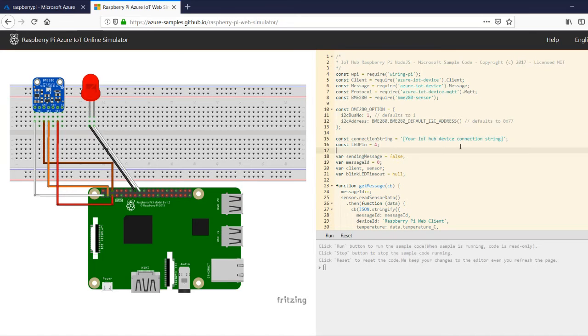Now just to give you a brief overview, this little box here is a Raspberry Pi. Like I was saying, it has 4 USB ports, 2 here and 2 here. This is an Ethernet port where you can connect your RJ45 connector. This is an audio out connector. And this little white strip is where you can connect a camera, like you see here closely. Notice it's written camera right here. This is an HDMI port which you can connect your external HDMI compatible monitor or a TV. This is a power supply, and this is where you can connect your MMC card for the operating system.